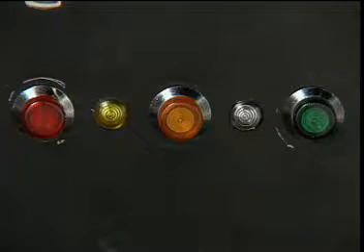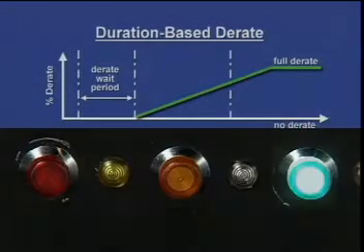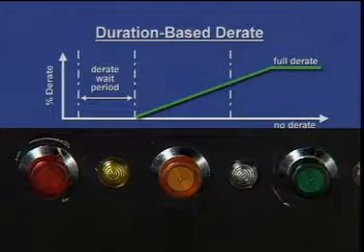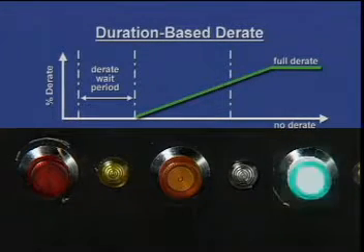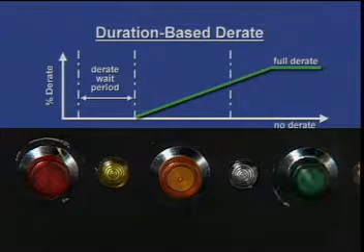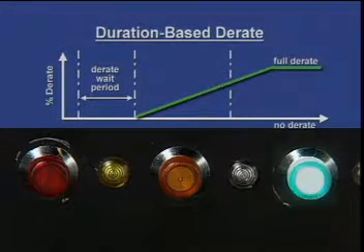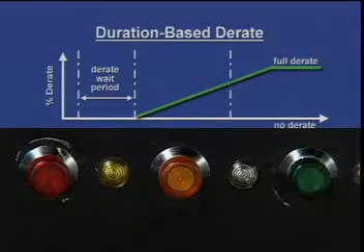The engine protection lamp illuminates when an out-of-range condition occurs. If the engine protection system lamp illuminates during engine operation, this indicates that a fault code has been recorded. The lamp will remain on as long as the fault is active. If shutdown is enabled, the lamp flashes to indicate an approaching engine shutdown. When this type of fault remains active, the engine power and/or engine speed will be gradually reduced. If the engine protection shutdown feature is enabled in the calibration, the engine will shut down after a short time delay to prevent engine damage.